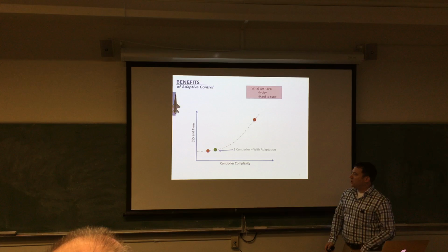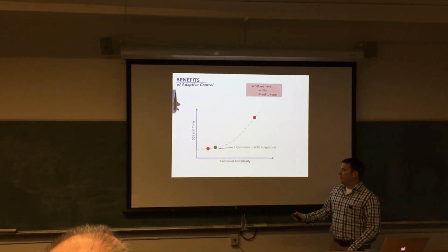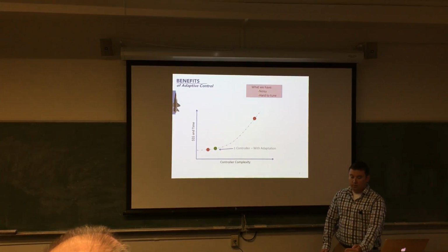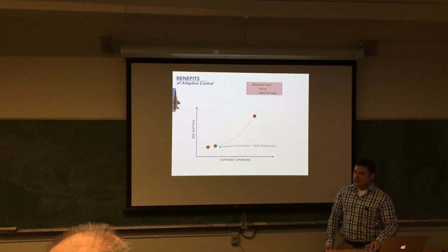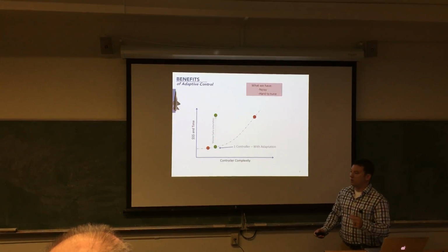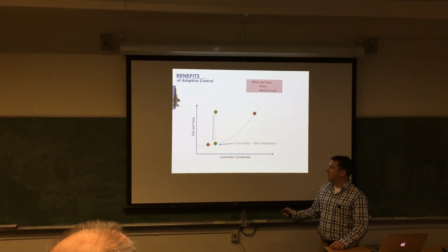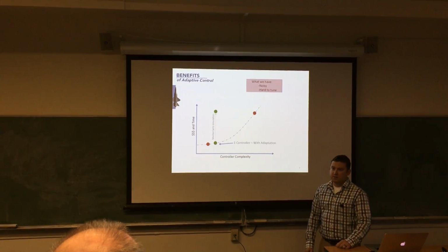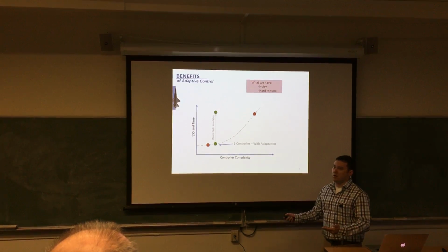So the idea is, hey, could we use one controller that's an adaptive controller, arguably slightly more complex, but relatively the same cost? And what you see is that some of the older adaptive controllers, like model reference adaptive control, ended up actually being equally as expensive, because to tune them and get the noise characteristics from blowing up and decreasing your robustness, it required a lot of Monte Carlo simulation, and you're right back where you started, right? So it's still the same problem. You spend flight test money or wind tunnel money, or you spend Monte Carlo money.